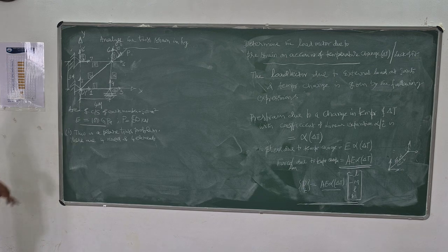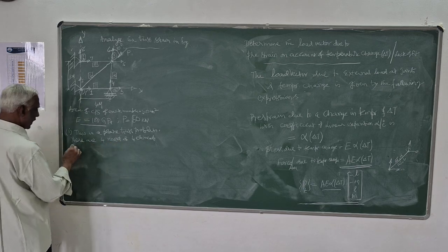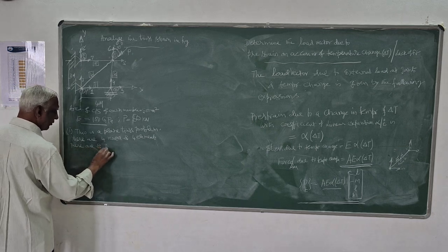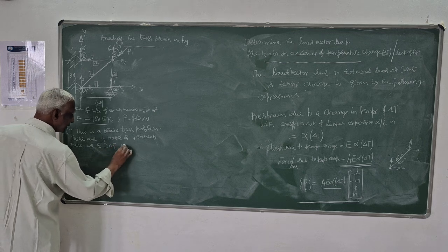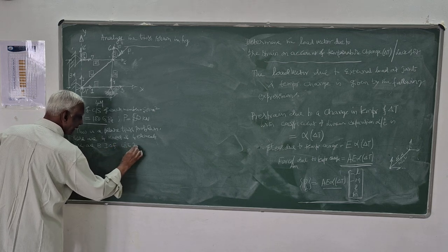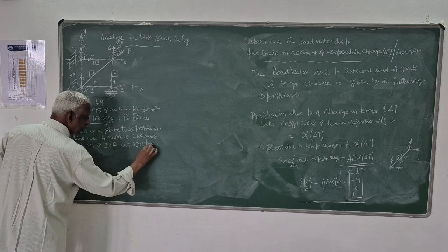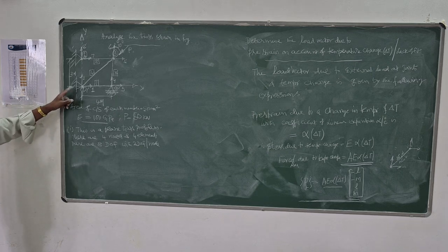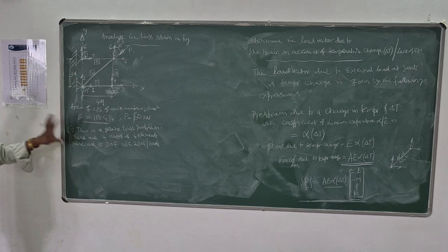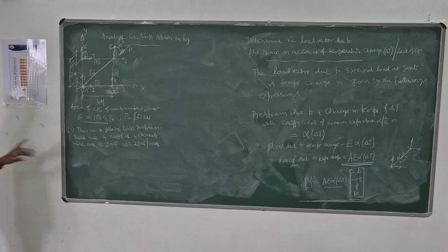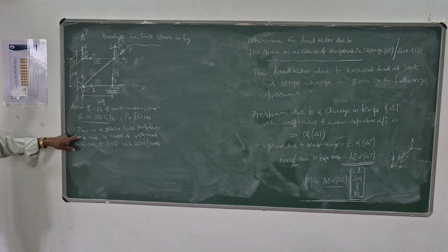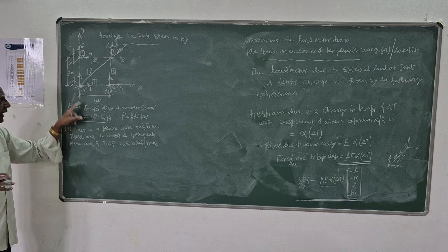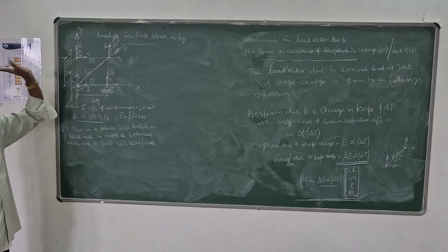So there are 8 degrees of freedom, 4 nodes, 4 elements, and 8 degrees of freedom with 2 degrees of freedom per node. Both are translations, no rotations, because each joint is a pin joint. This is the basic information first put together: how many elements, how many nodes, what is the total degrees of freedom, and out of these 8 degrees of freedom, some are restrained.